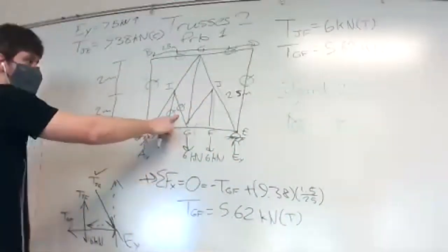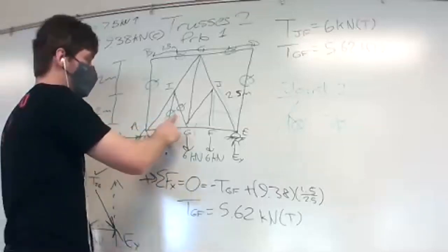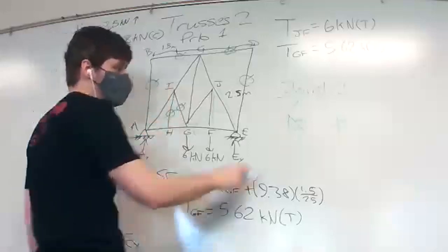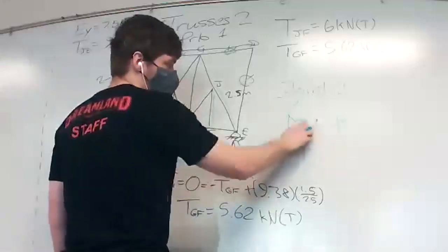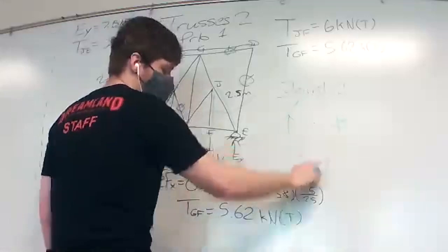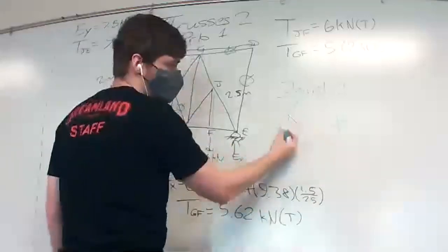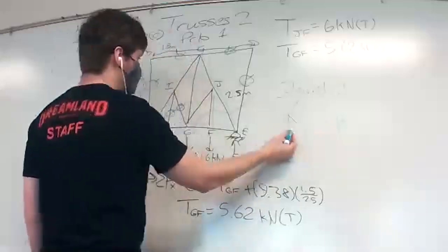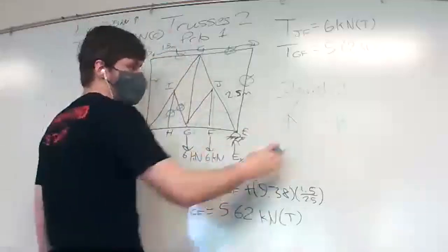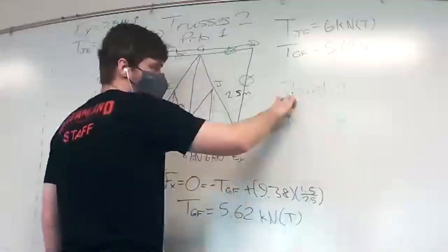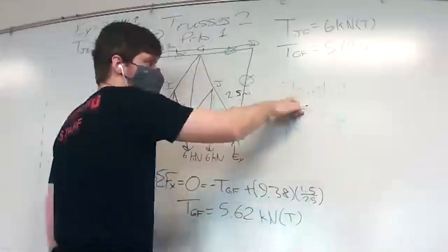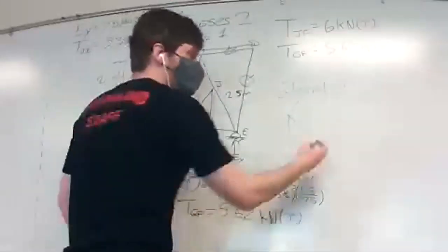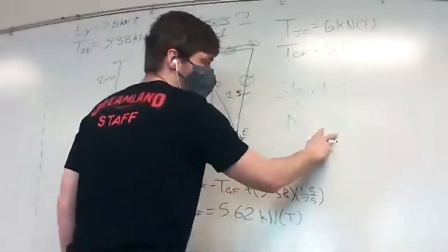So how did you determine that? We determined it was 0 because we already know that HI is 0. So when we have this shape where these two members line up, and we have a member coming out of it like this, you can turn it and make it so that your new Y direction has these two members.